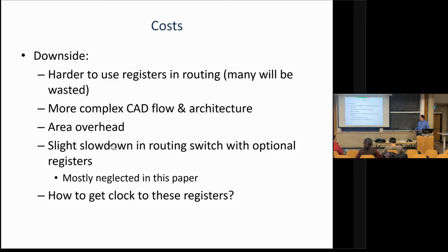So it's like, if you were using them as a normal register, your placer is going, okay, I'm going to put this in the routing, that's obviously not going to work. Yeah. If you go with a flow where your placer says, I'm putting this inside of the logic block, and then your router does a path, and after you're done the routing, you go, okay, actually my path happens to go through a register, and my register happens to meet the synchronous clear, whatever requirements. So I'm just going to move that, which was previously in a logic block, and now it's in the routing. I think this is still harder to use, right? You're basically saying the CAD flow kind of ignores them till the end, or assumes they're going to happen and tries to use them later. That's still harder to use.